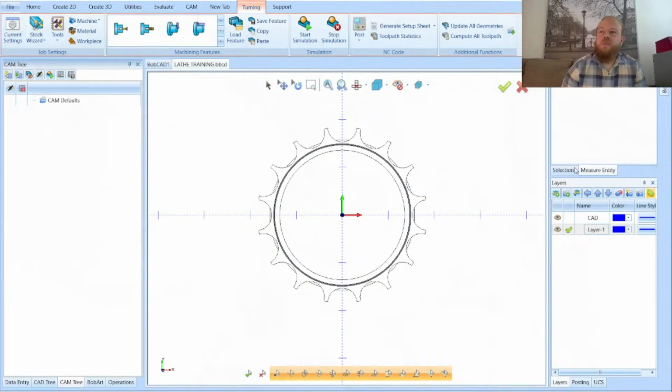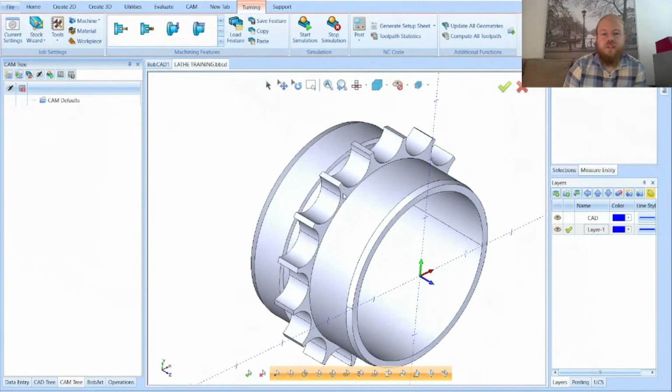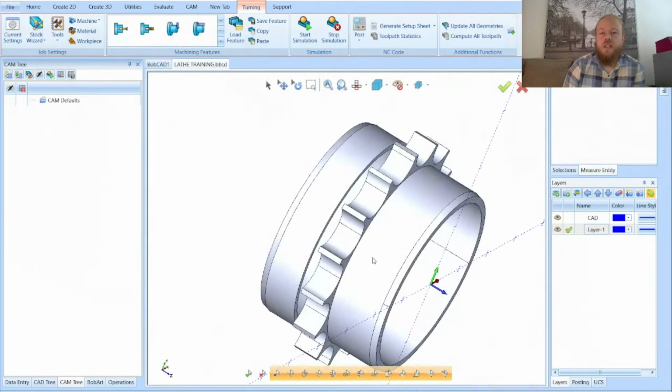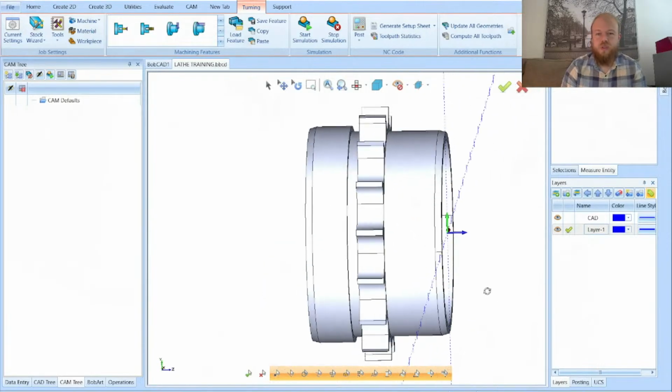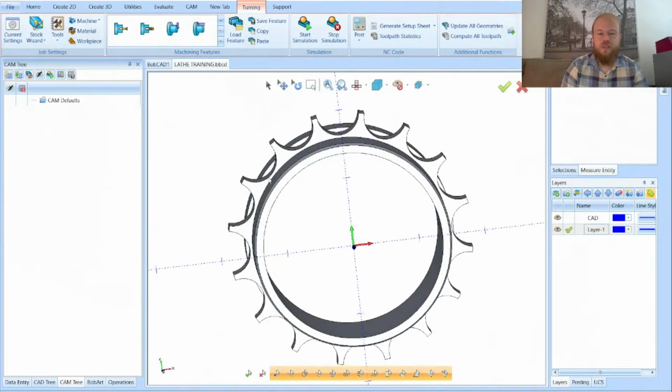All right, we'll get started today. Today is on lathe features, specifically advanced CNC lathe strategies. So I've got a part file here. You may be looking at it and thinking, well, you can't really turn down the part completely, especially with these areas here, that profile around it. But we'll be looking at strategies on how to turn the areas that we can on this part, create geometry to turn down the stock if we're looking at it from this sort of view here, turning down to this area so that we can use a milling tool or something to mill around the profile afterward.